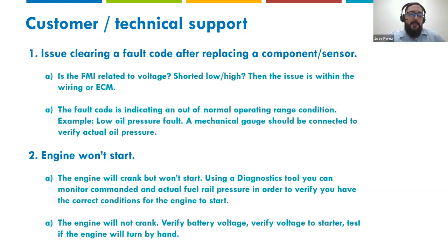With customer support or technical support, they would guide you in the right direction. So, for example, is the FMI related to voltage? Do you have a shorted low or shorted high FMI indicator? If yes, then the issue is with the wiring or ECM, right?